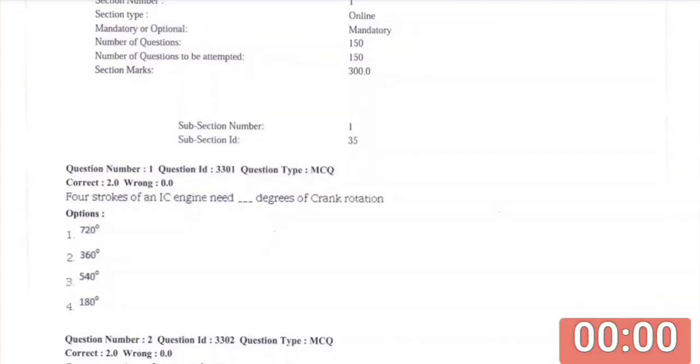This stroke produces mechanical work from the engine to turn the crankshaft. Hence, this stroke is very important while studying the IC engine. Fourth stroke is exhaust stroke, also known as outlet. During the exhaust stroke, the piston once again returns from the BDC to TDC while the exhaust valve is open. The action expels the spent air-fuel mixture to the exhaust port.